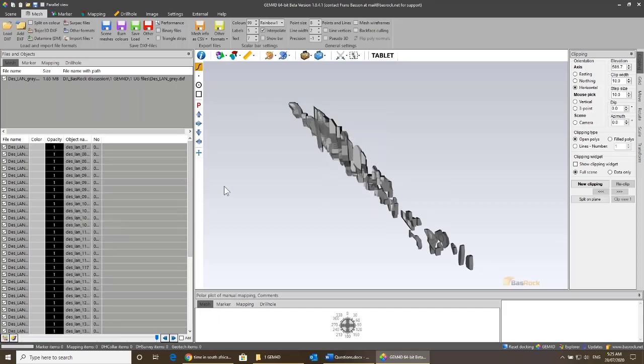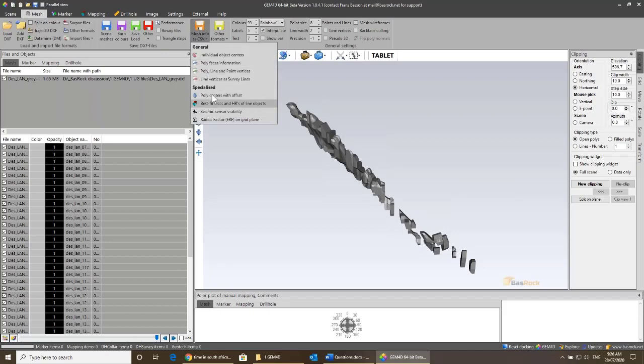One of the things that people sometimes want to do is have the center point of every object saved out separately as a point. Then that point, which is now the center point of my stope, represents a lot of properties for that stope, and you can give it hydraulic radius and risk models and a whole bunch of stuff. So you take this, you say mesh, export, you go to the ribbon, export files, and say I want to save the mesh info as a CSV file. You'll see there's a whole bunch of options.